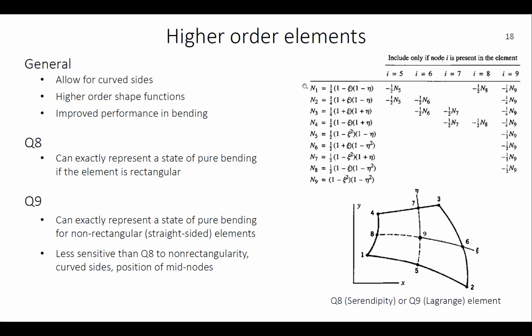So you have the first 4 shape functions, which are just the bilinear functions, and then you have second order polynomials in each of the xi and eta directions, which are represented by each of the sides of the element. So it will have a second order polynomial along one direction here, and then linear in the other direction. And doing so for the 4 different sides.